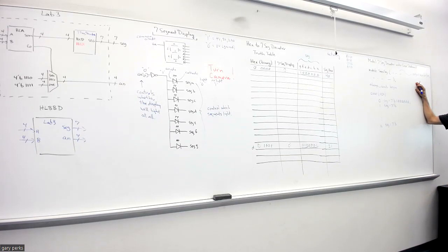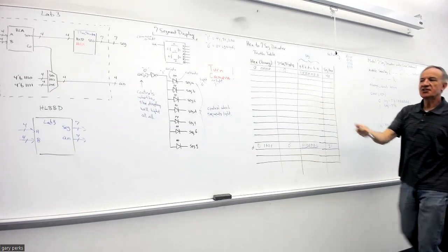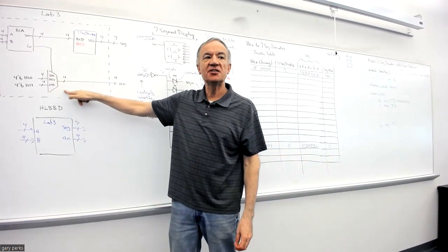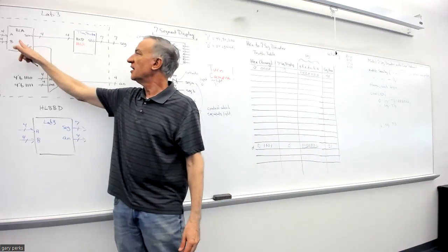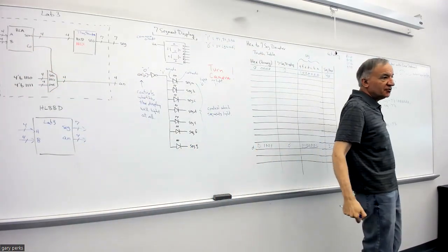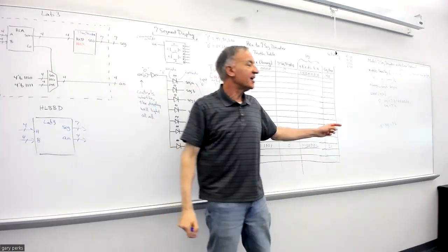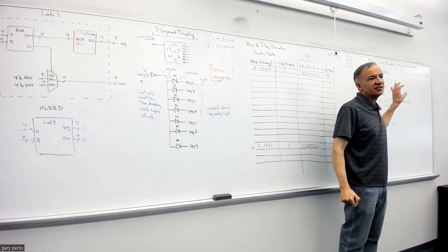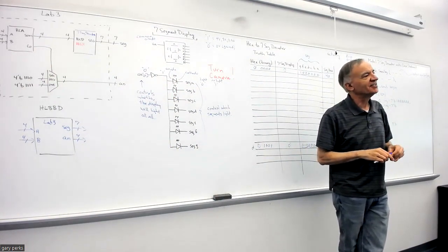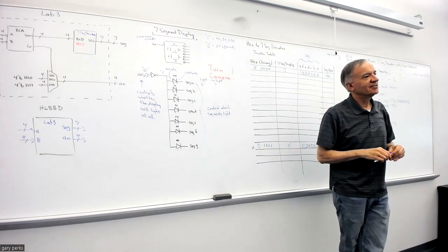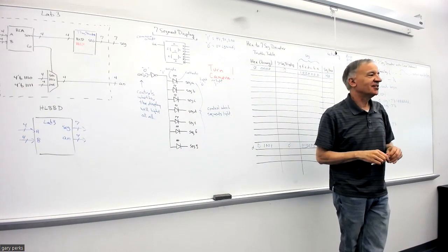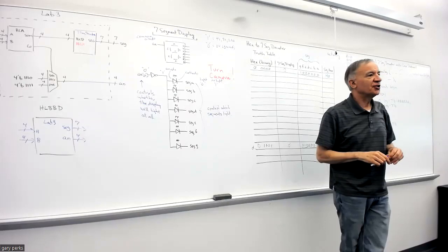Yeah, you bring up a good point that, just like you had to simulate your mux, and some of you did that last time, but if you haven't simulated the mux yet, you probably want to start with that. You had to simulate the RCA last lab. Well, after you're done with this design source, you need to simulate this decoder. So you're going to have a test bench for your decoder. And how many test cases is the decoder test bench going to have? How many rows in the truth table do we have? 16. So you're going to have 16 test cases for your decoder.